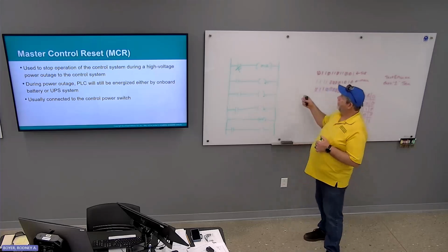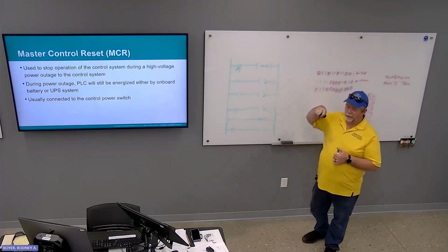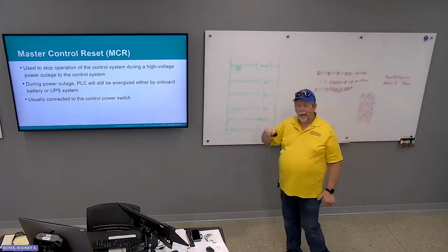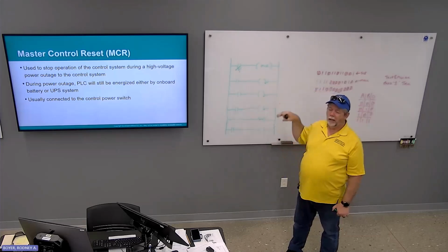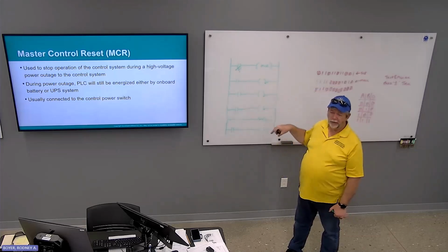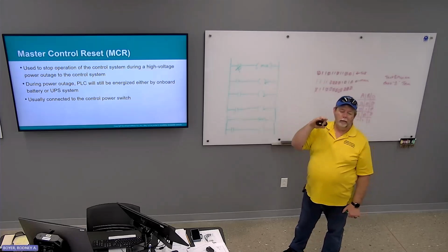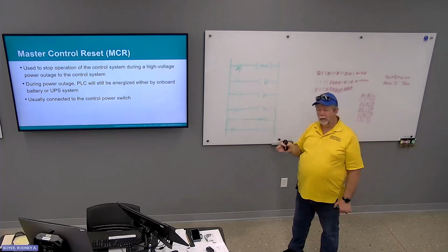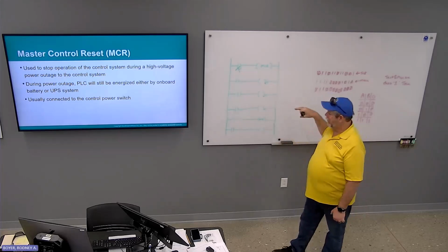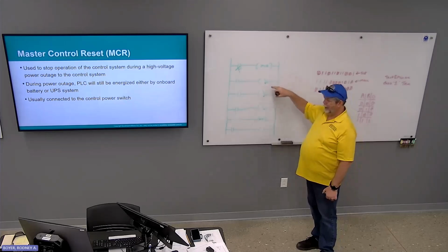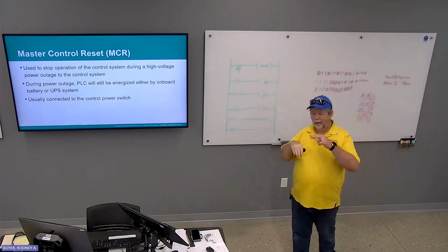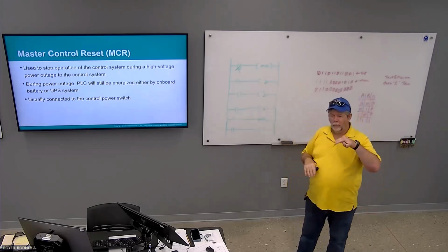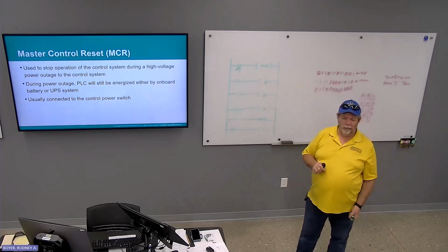Anyway, jump, label, the conditional logic in front of the jump instruction has to evaluate as true for it to do the jump. It does not update any output instructions while it's jumping. MCR, the conditional logic has to evaluate as false for the master control to work, and any output instructions between the two MCR instructions will clear to zero.